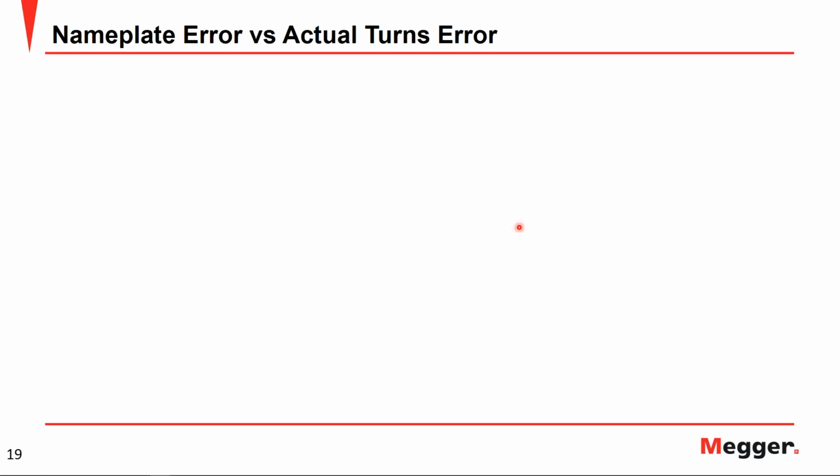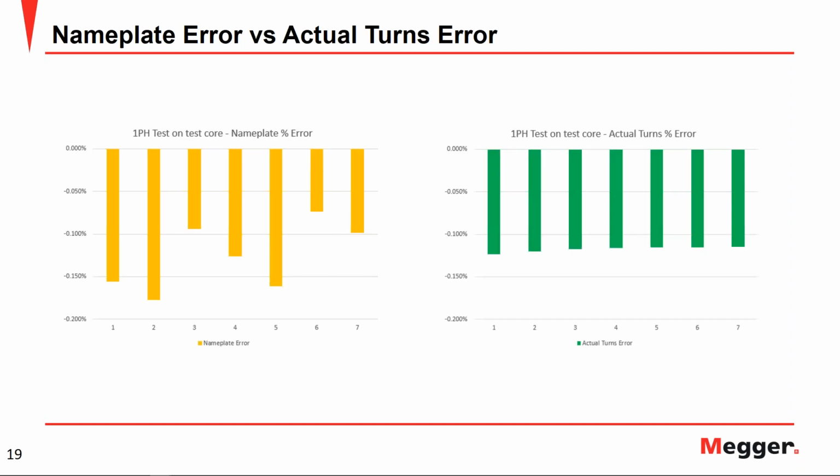Okay, well, this is obviously referring to a slide in the presentation. I don't know if we can go to that one, but in the meantime, I can tell you. Remember, when any type of tap changer, whether de-energized or on load tap changer, is involved in our testing, especially for a commissioning where we want to make sure the tap changer was wired correctly and is working as expected, you have to run the test through all the positions of the tap changer, when possible.